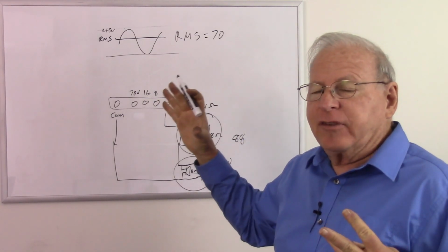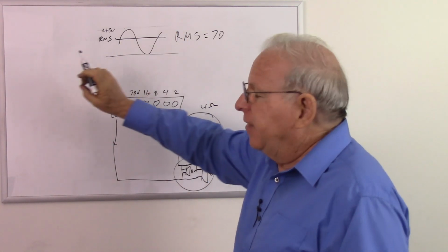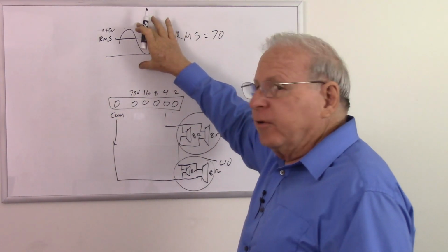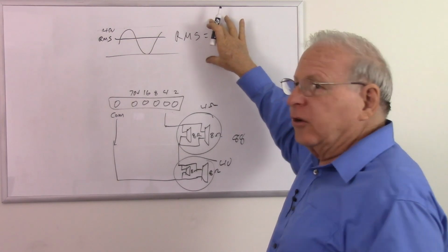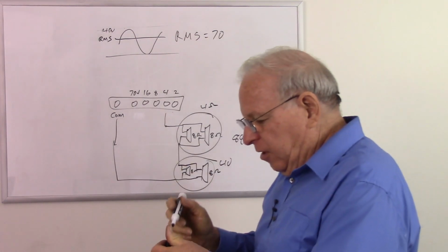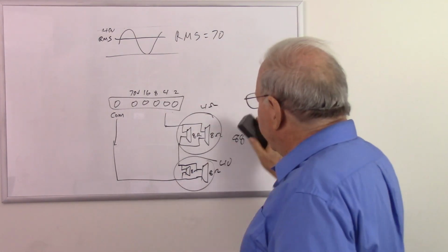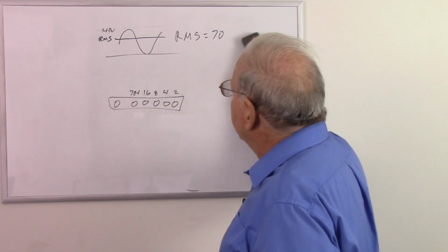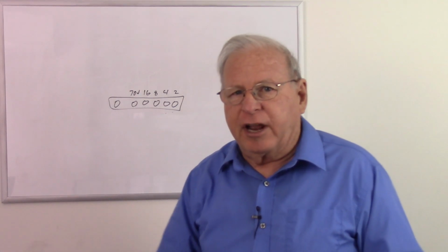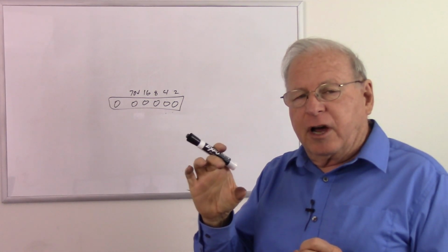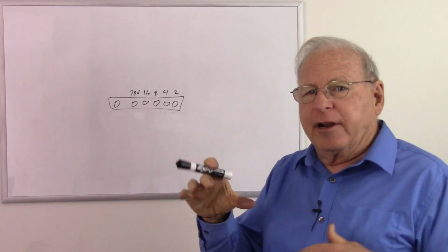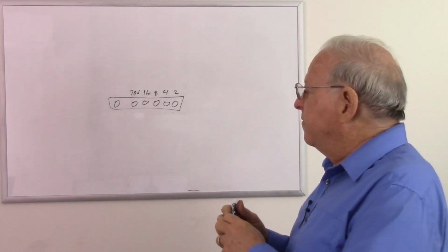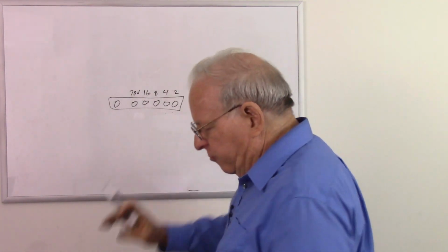It's going to adjust its output impedance to make sure that when it's producing its loudest output, that is going to produce a 70 volt RMS signal if it's a sine wave. So all we need to know though is that we need to set up the speakers for that 70 volt system. So how does that work? Well, in that case, the speakers have transformers. You might buy speakers with a riveted on transformer with several taps on it, or you might buy raw speakers and then have a transformer that goes between it and the amplifier. Let's assume that we have a transformer.